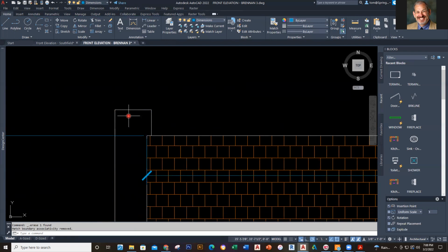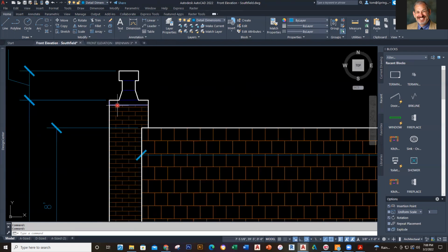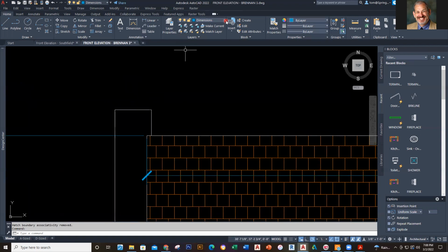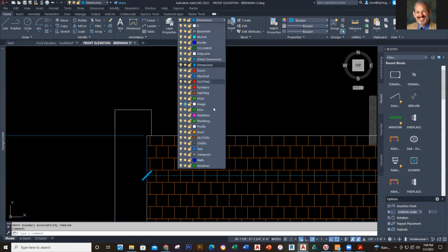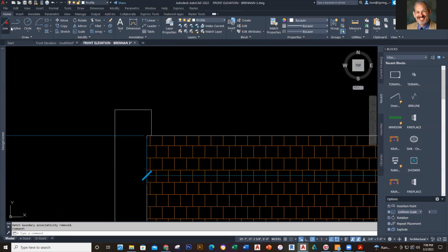That's okay. So when I do this right here, it's actually a 1-inch cap right there. And then I would go ahead and draw this object out, which uses the dimensions that we talked about. So I'll go back to here and use my profile and go line, and I'm going to go down here, because first of all I have to go down 1 inch. So 1 inch down and then 1 inch over like that. Is that 1 inch? Hang on, let me look here. It's 3 inches down. Ah, wrong about that. So I want to go down 3 inches. So I'll undo this and go down 3 inches. And that gives me that look right there.